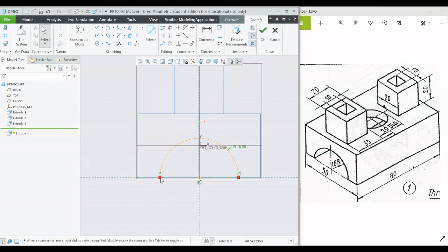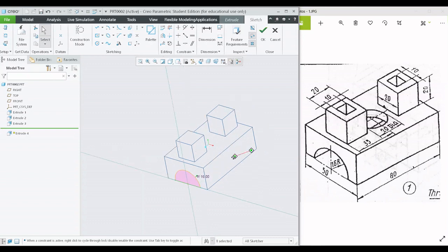I am able to get these shaded blocks because this feature is turned on, highlight open ends. So see that you also keep this feature turned on. I need to make this sketch a closed loop, so I click on line and simply connect the 2 edges. So my sketch is ready right now.